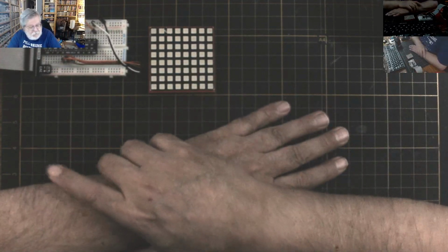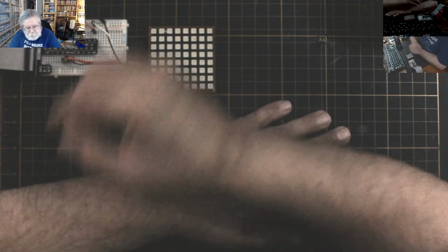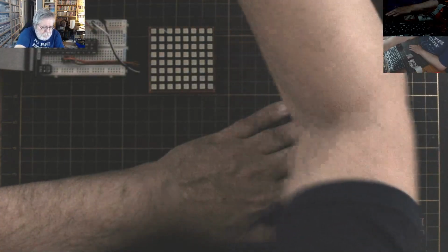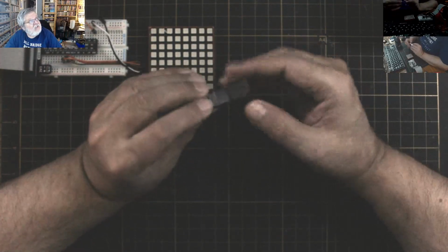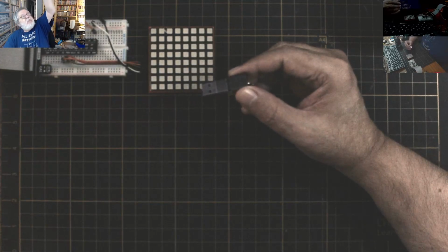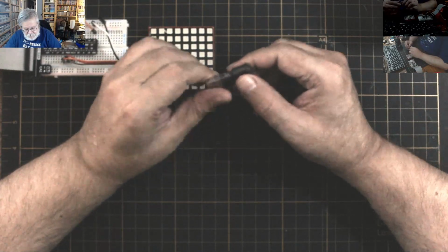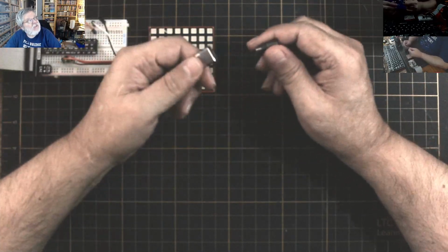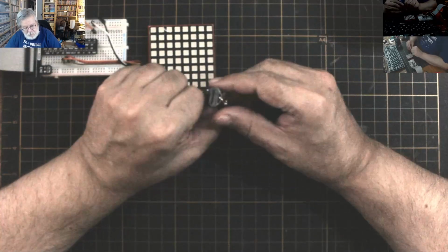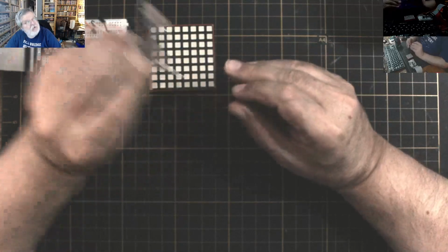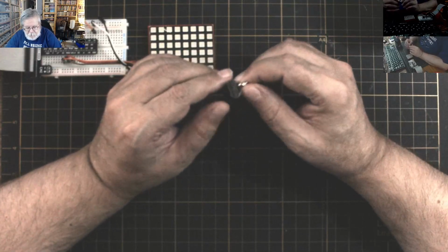Now, when you prep the OS on the Raspberry Pi, after you install it, you put it on a key. You're going to need a tool to do it. Either one of those card readers or whatever. I found this guy handy. Let me just turn the brightness a little bit more up. There we go. This guy here is an adapter, and this is a USB-C writer, like so. You stick your little micro SD card in here, you stick it in your USB hub, and you flash. Just use the Raspberry Pi Imager to put the OS down.